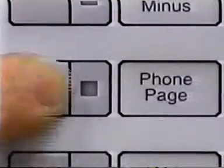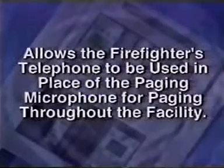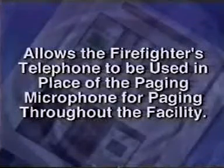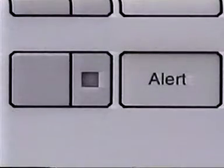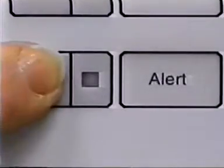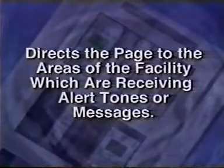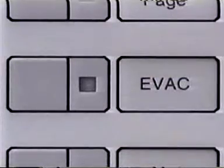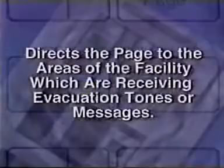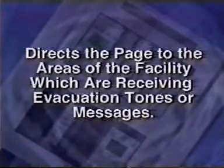The phone page switch LED also has a green LED and indicates a phone page mode, which allows the firefighter's phone to be used in place of the paging microphone for paging throughout the facility. The alert switch LED with its green LED indicates that the 3ASU is in alert mode. Pressing the alert switch directs the page to areas of the facility which are receiving the alert tones or messages. And finally, the evac switch LED with its green LED indicates the evac mode. Pressing this switch directs the page to areas of the facility which are receiving the evacuation tones or messages.